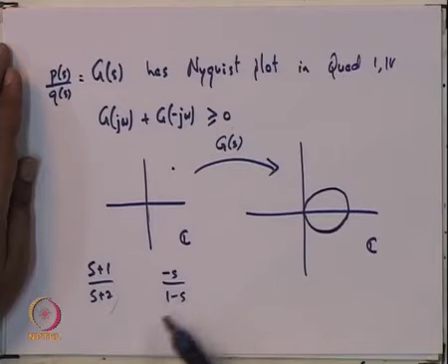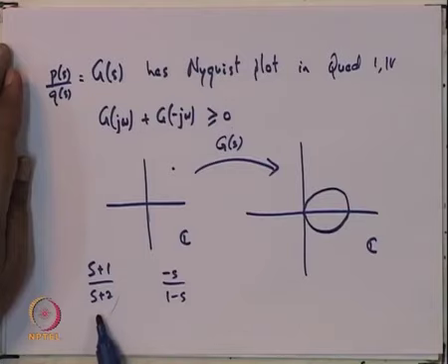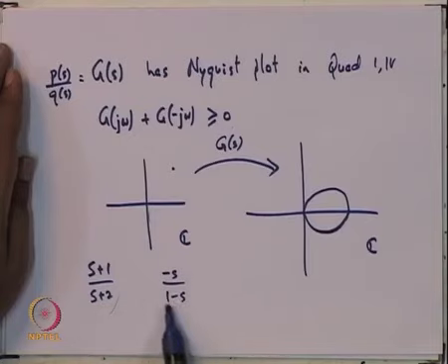Earlier I had also talked about the idea of dissipativity and the idea of storage function. So, in both these cases you will get a storage function. The only difference between these two is that in this case, because the denominator has all its roots in the left half plane, that means this is a stable transfer function. Therefore, in this particular case the storage function that you get is positive. On the other hand, in this case also you can construct a storage function, but this storage function is not going to be positive, it is going to be negative.